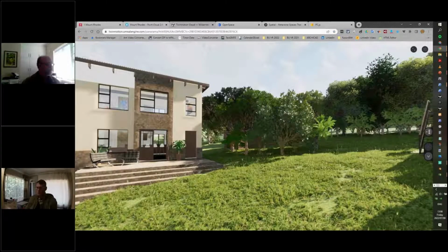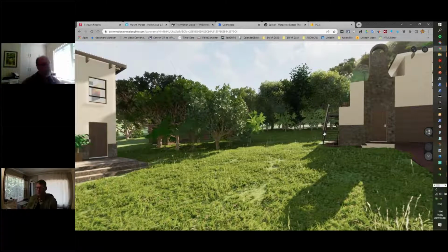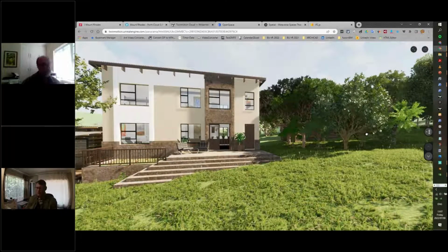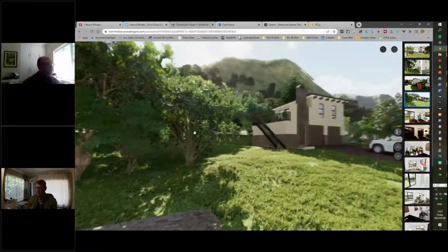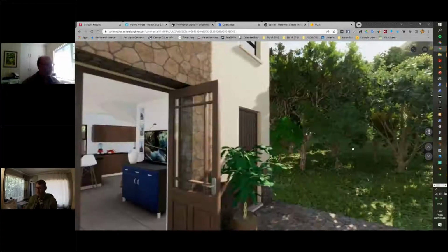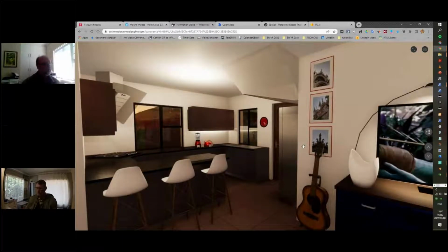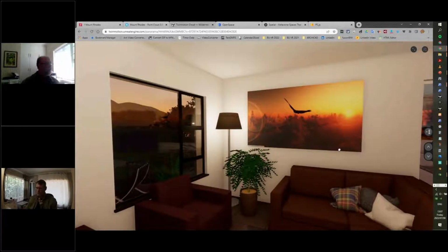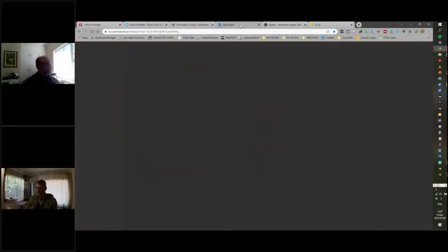So when we talk about Twinmotion, what you see here is a panorama set. It's rendered from an Archicad model into panoramas and then published to the new Twinmotion Cloud platform. You can set up your different views and then teleport and navigate to the different panoramas, where you can actually have a 360 view of your rendered scene. You can also just click on the hotspots in the scene and navigate to those hotspots, and you can render in different scene modes. So that is one of the outputs quickly.